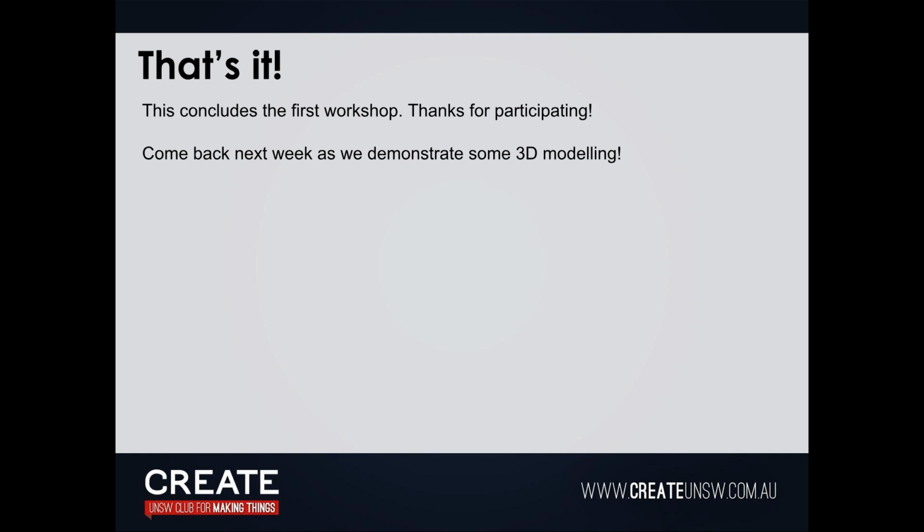What we'll do next is combine it once again. We can make that a new component again. You could make a component from a body. Actually, that's already done. Right click on body 12. That's already a body. You right click on it, create components from bodies. Click on that. Now you have 2 components: component 1.1 and component 2.1.